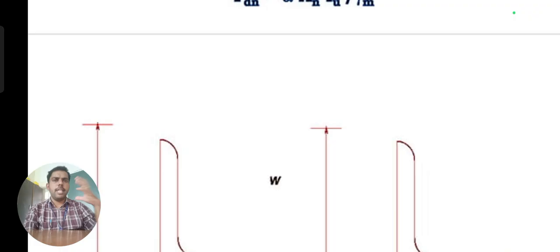These all are steps. This is the design part of the tension member. Any design member you have to design, first of all, you have to take the cross sectional area due to that load. After that, based upon that cross sectional area, we have to consider one particular angle section or any I section or C section from the steel tables. After that, we have to provide the connection. For that connection, we take the values of strength in single shear and strength in bearing. Based on these values, I have to take the lesser value and find out the number of bolts for fixing the gusset plate to angle section.